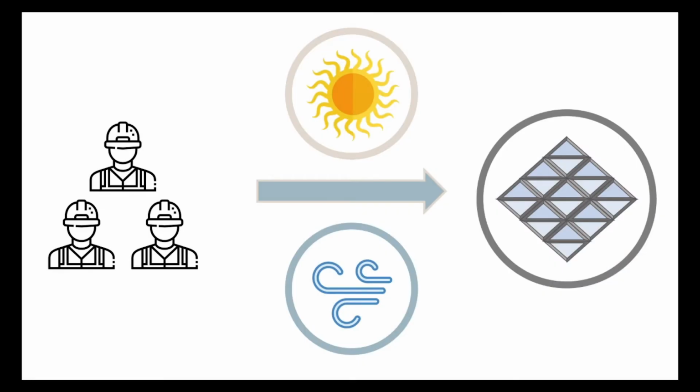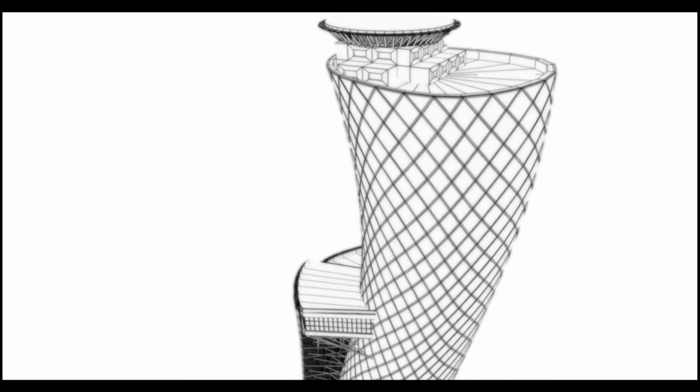Keeping these climate conditions in consideration, the construction team had to find reasonable solutions to realize this complex facade with glass panels. It should have the capacity to accommodate additional movement caused by wind and temperature changes, which would expand or contract all the steel beams and glass panels.